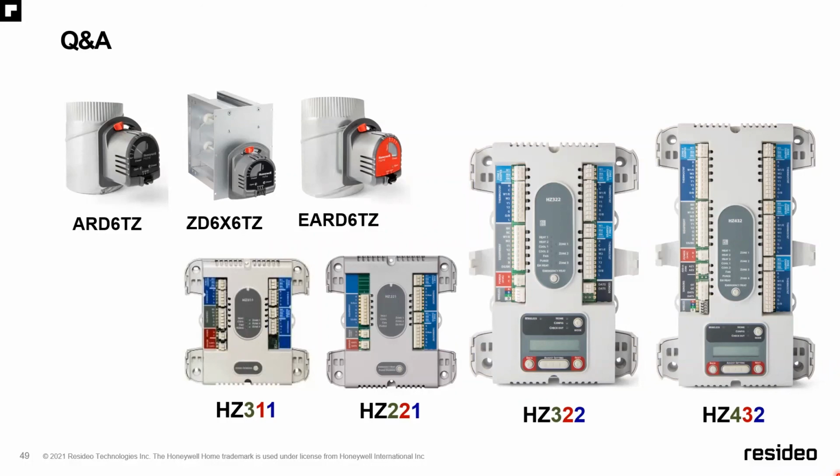I do understand why that question's being asked, but it's been my experience that because we are sending so many BTUs of cooling capacity or heating capacity to a single portion of the house, we can typically take care of that temperature call quickly enough that that doesn't tend to be a factor.